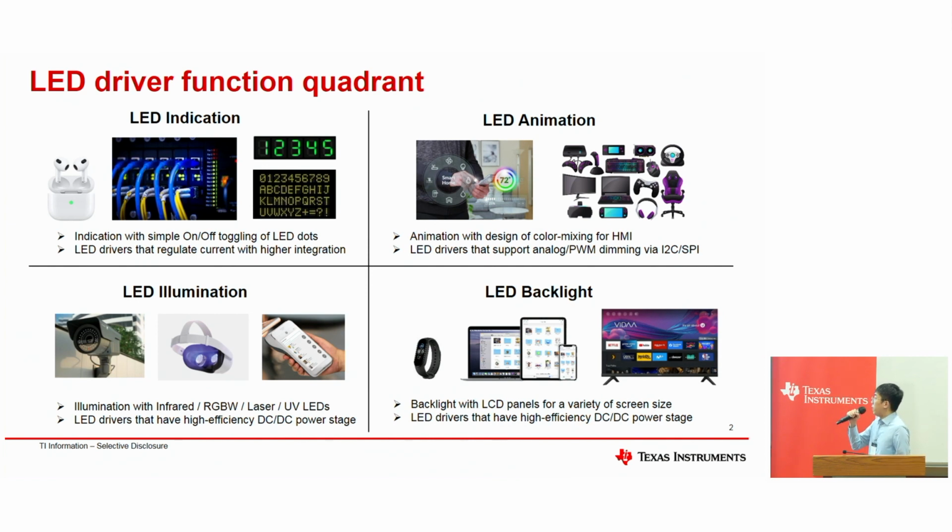Also similar to the illumination, the backlight LED driver will utilize a high efficiency DC-DC power stage. Specifically, it will use boost topologies, because when you are inputting 12 volts or 20 volts and about to drive 10 or 20 LEDs in series, that will generate a larger, up to 40 volts, forward voltage. So for the LED backlight modules, you probably want to use boost topologies in terms of the applications.